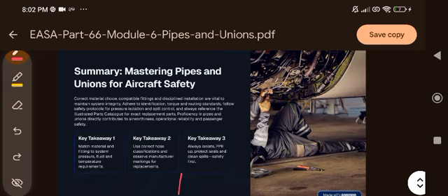Match material and fitting to system pressure, fluid, and temperature requirements. Use correct hose classification and observe manufacturer markings for replacements. Always isolate, PPE up, personal protective equipment up, protect seals and clean spills.